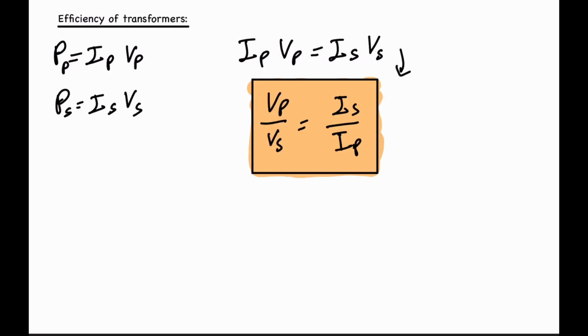So we talked about eddy currents being formed, which reduce the efficiency of transformers. Another way efficiency is reduced is through the resistance in the coils themselves. Because you have a really long coil of wire, you can expect a lot of resistance. So heat is generated in the resistance of the coils, which causes a reduction in efficiency.